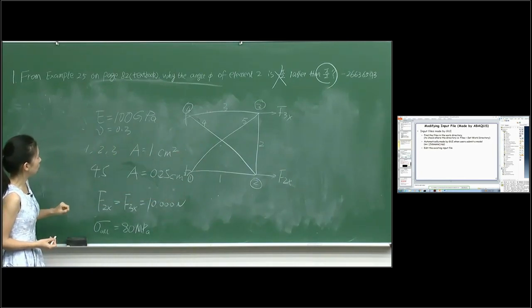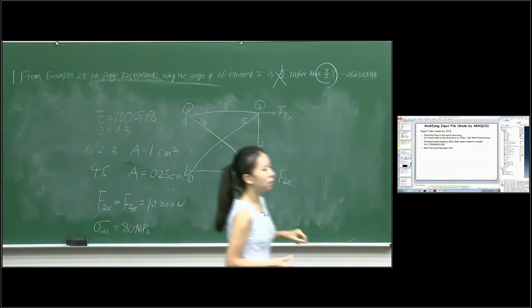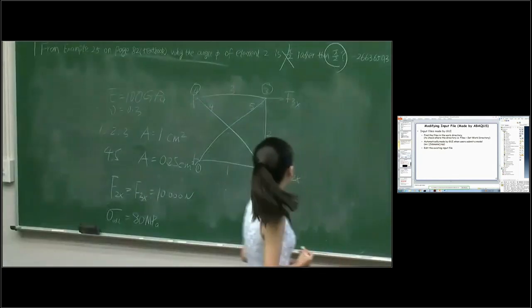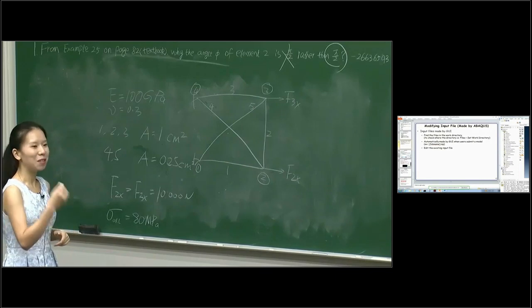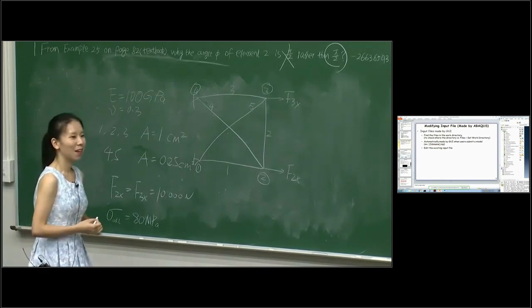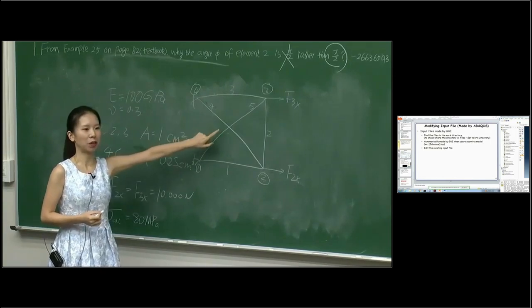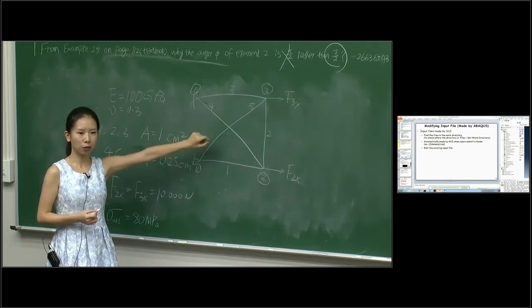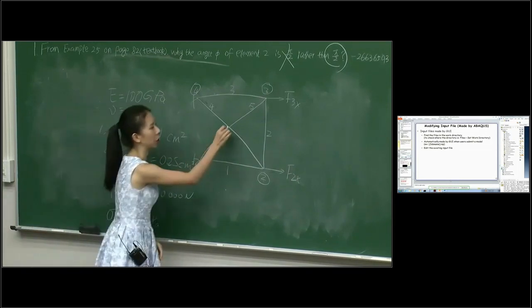And for the diagonal truss, any question? I was wondering, how come you didn't define a node in the middle where the elements intersect? I will say later. So the problem is there shouldn't be any node here. But when I use ABAQUS to sketch this problem, it will automatically generate a node here.